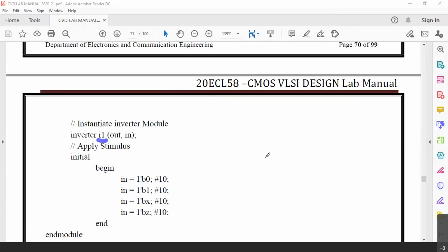Now, as such, Verilog is concurrent. All HDLs are basically concurrent. In the sense, when we write all these lines in the code, the lines will not follow a particular sequence. It is concurrent, means at once the execution is going to happen. But whenever we give the statement such as always or initial, we are making the concurrent execution a sequential execution now.